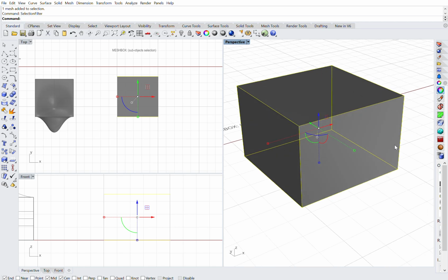For this mesh, if you tick sub-objects, more words come up: points / vertices. Points basically refer to NURBS geometry. The vertices are for the mesh, similar to surfaces for the NURBS and faces for the mesh, and likewise curves for the NURBS geometry, and edges is a term used for a mesh.